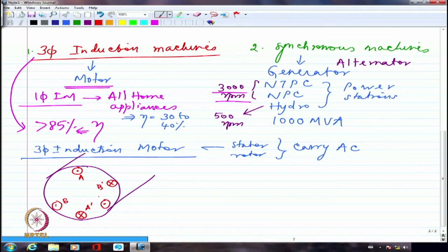Right? I have shown it as though it is only one winding. Definitely it is not only one turn. There will be multiple turns. So I should show as though the A winding is spreading over the entire inner periphery of the stator. But generally, when I have A phase, B phase and C phase windings like this, it's not going to be easy, even machine-wise, to wind the entire winding without getting confused. It's going to be pretty difficult.